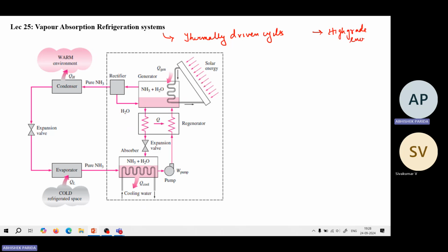That is why you will find that COP is mostly more than 4. Nowadays VCRS systems are above 5, and COP can even go to 10, but on average it will vary between 5 to 7.